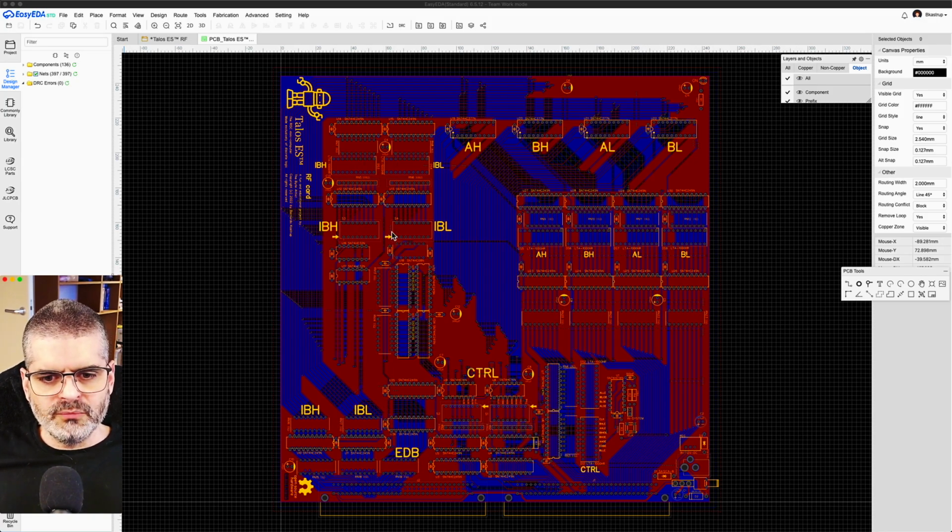Then we have the 2 dip switches with which we can drive the high byte and the low byte of the internal bus. They have their own drivers and the resistor network here to pull the values down so the switch works. And the buses can be driven from these 2 switches here, S3 and S4, which drive the local bus or the internal bus lines here along the left side of this card. These 3 chips are the control logic we talked about.